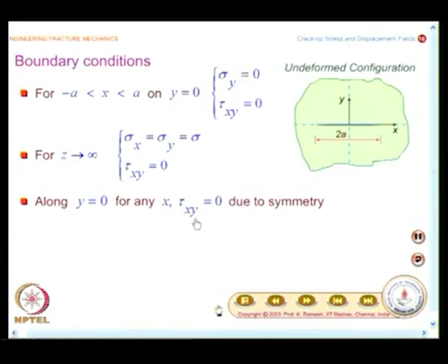And you have to distinguish, this is an in-plane shear stress, we are talking about tau xy. See, in this course I said I am going to investigate whether the solution obtained from fracture mechanics is correct or not, whether some modifications need to be looked at. I said I am going to use photoelasticity.